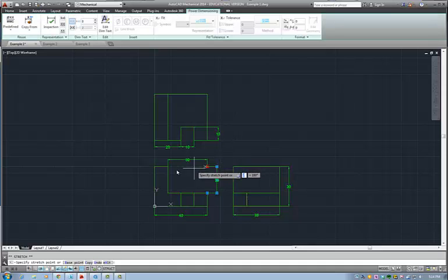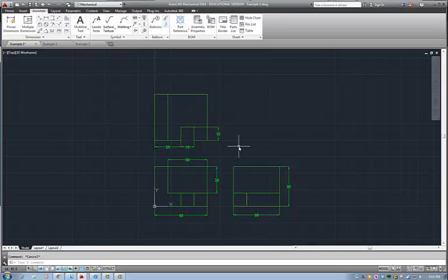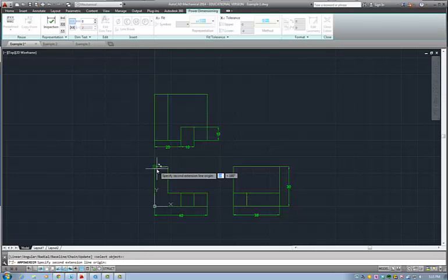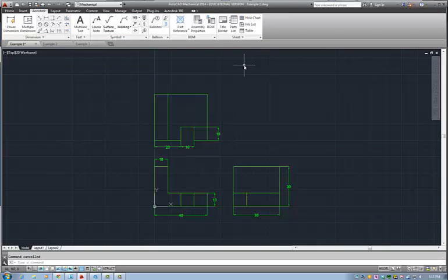But the way it is right now, this has to be attached to the part. So you see, I could dimension what I'm going to remove, like I did here, or I can dimension what I have left, but don't add both of these. So either what you have left, this is easier to understand for the quality control, or like I mentioned before, what you want to remove. So this would be example 1.